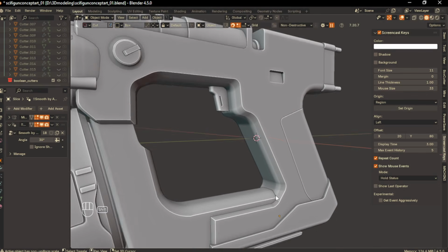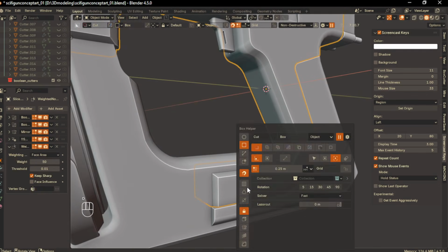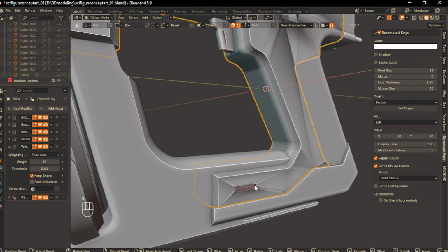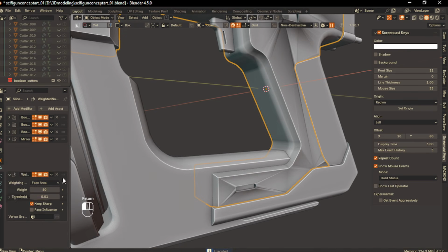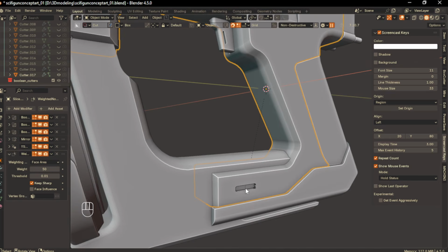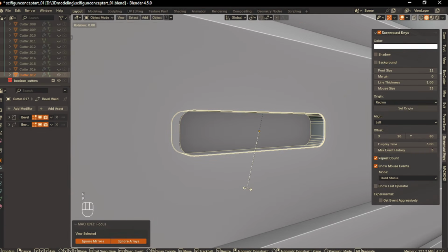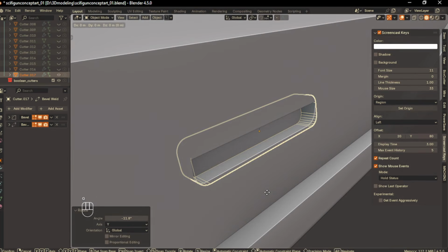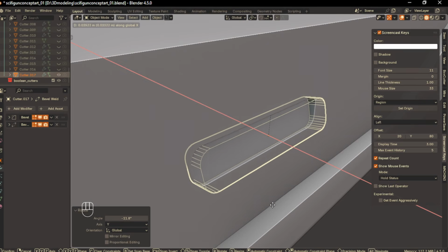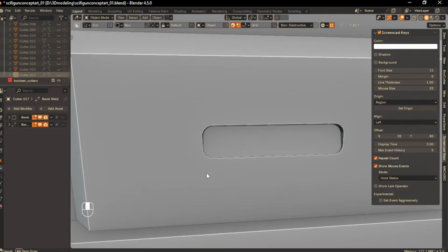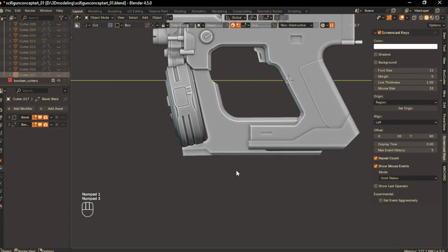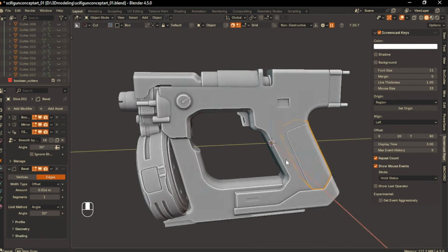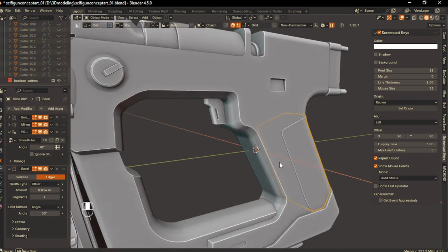Now let's try the same trick on different places. I think here we have some spacing, so I'm drawing a rectangle, pushing it in and beveling it and hit enter. Now enable the cutter, rotate it on the Y like that and bring it forward. Just a closer. Yeah, that's awesome. This is just a simple cutter trick you can use in your model to bring that mechanical and industrial look instantly.